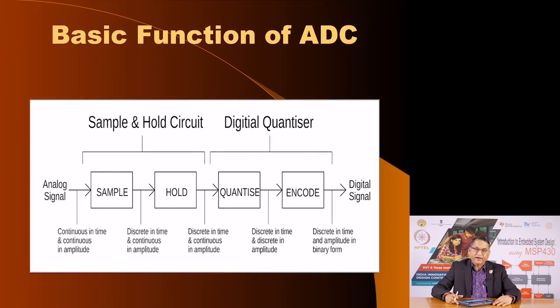This is how an ADC works. You have the analog signal in the form of the output of a particular sensor or voltage. You need to sample it, that is, you decide at what point of time you want to look at this value. Now, the input is asynchronous, meaning it can change whenever it wants to. But while the conversion process from the analog voltage into a digital number is in process, you do not want the input voltage to change. So, you include a circuit which can hold the analog voltage at the value it had when you start the conversion, and hold it till the conversion is over. Such a circuit is called a sample and hold circuit.